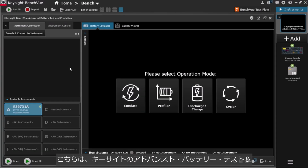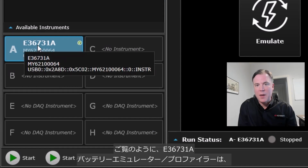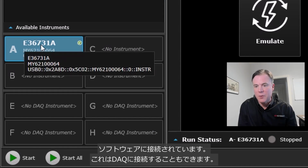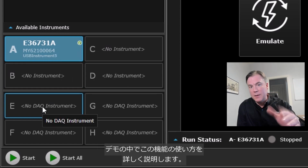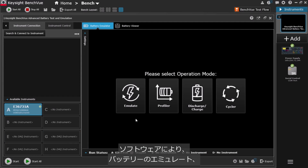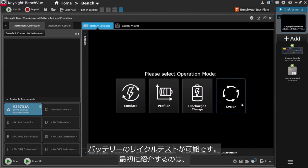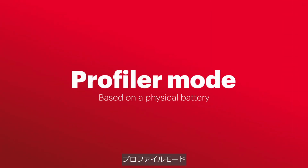So here I am within Keysight's advanced battery test and emulation software solution. You can see I have an E36731A battery emulator and profiler connected to the software. You can also connect a DAC. In the demo, I will go into more detail on how you can use this functionality. With the software, you can emulate a battery, profile a battery, discharge a battery to perform a battery rundown test, and cycle a battery. I will start in profiler mode.